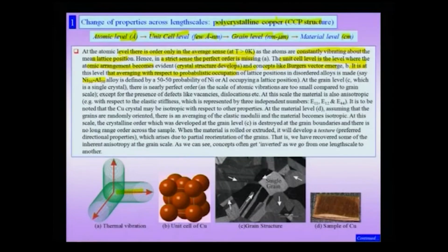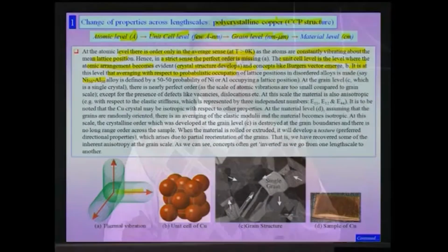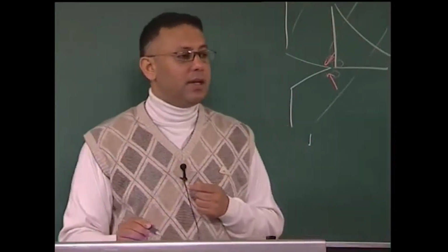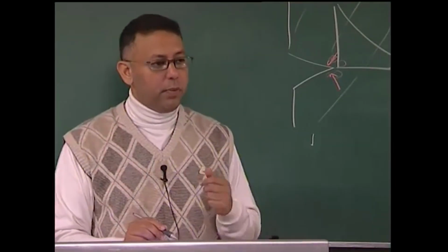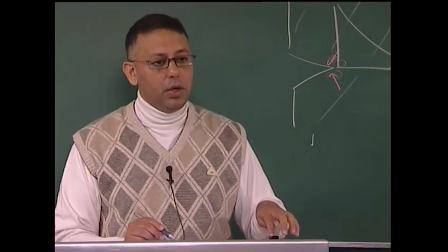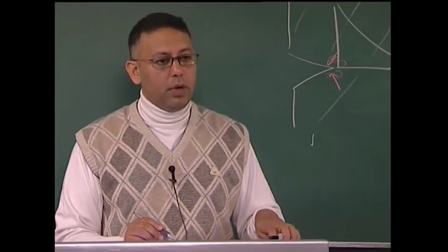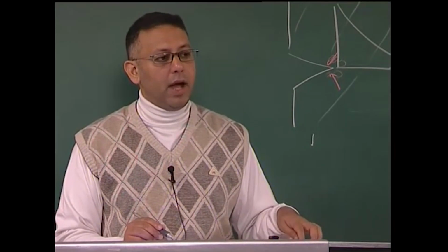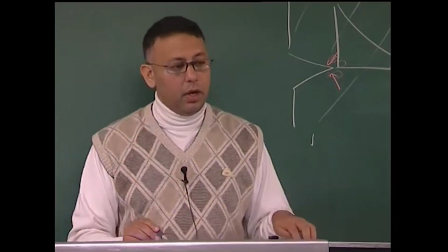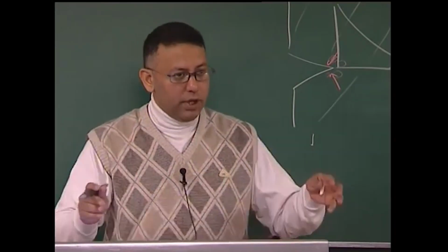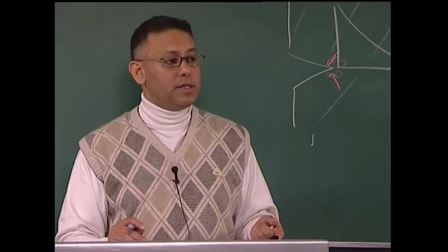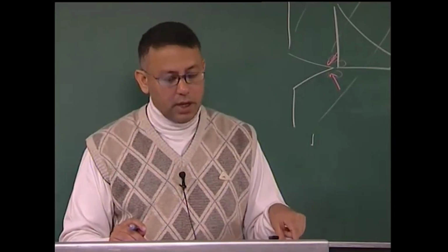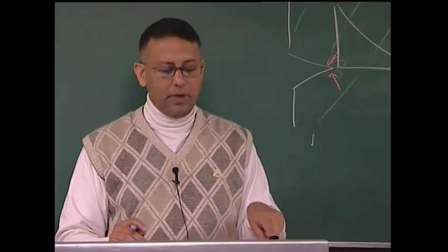We are actually digressing a little bit to an alternate example just to tell us where the averaging with respect to composition takes place. It takes place at this level of the unit cell. So, in an NiAl system with 50-50 possibility, if I take a single unit cell, I may notice that it may not contain 50% atoms of nickel or aluminum, but when I take a few unit cells or a larger cluster of unit cells and average out there, then I would notice that 50% of the atoms are nickel and 50% of the atoms are of aluminum.